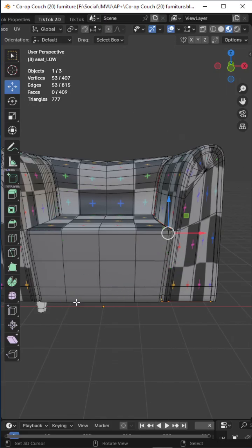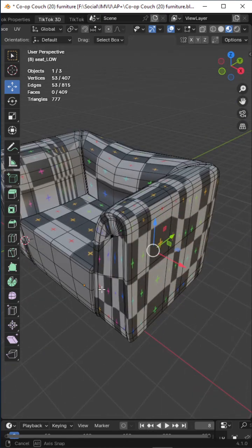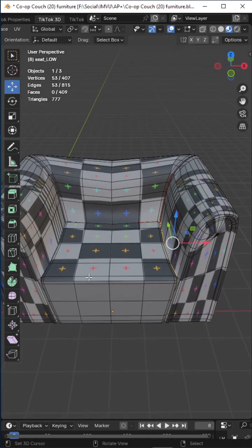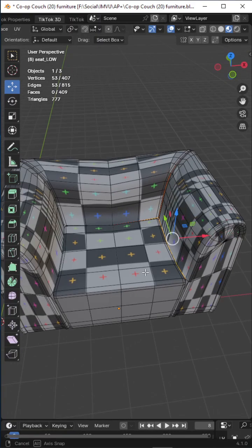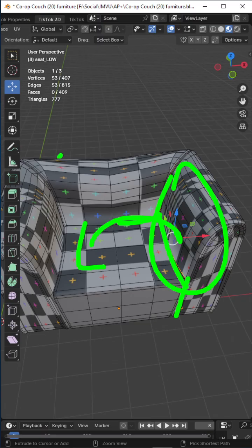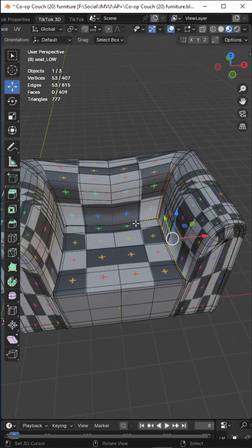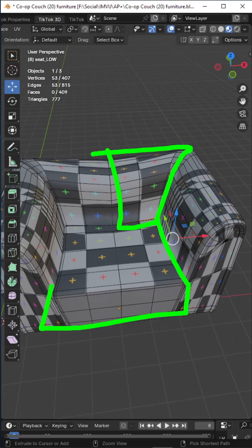So if we want a unique texture assigned to any objects, we have to make the mirrored section real before we can go further. So although we've done this basic seam assignment, we have to decide whether we want to just stick with the mirrored side, which will duplicate and invert the image, or whether we want to make the mirror side real and then unwrap relative to the entire object. So instead of unwrapping half a mesh, we unwrap the whole mesh.